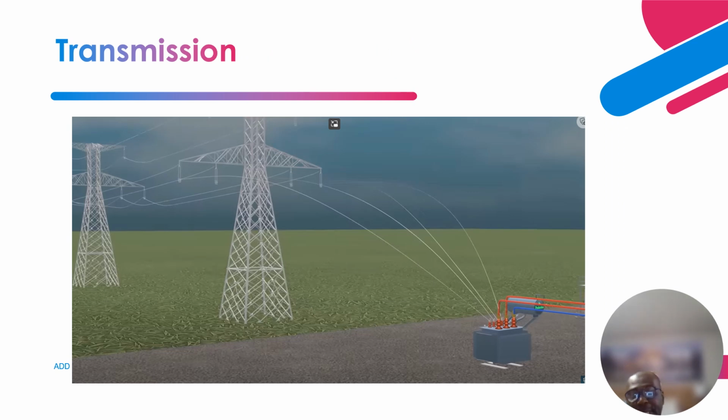This is basically the transmission end, the step up. At the terminal of the generator you have 13.8 kV, or 21 kV. It has to go through a step up transformer because you're going to transmit this voltage over long distances, hundreds to thousands of kilometers or miles. So it has to be stepped up to a higher voltage to minimize the transmission losses.